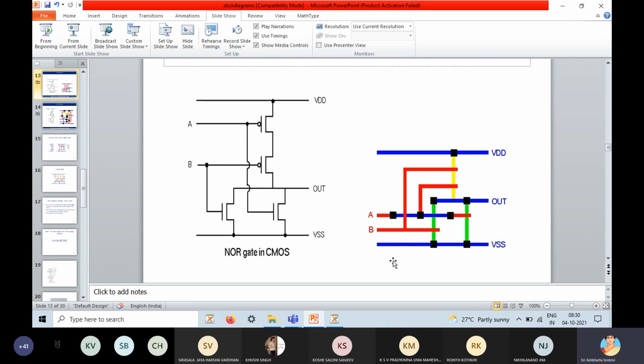So if it is like this for just a 2-input NOR gate, think about a complicated layout. We have to provide many vias, because here we cannot directly run polysilicon like this, because there are different layers. So that's why we have used these two vias, and we have used a metal. This metal layer and these two contacts are nothing but extra.